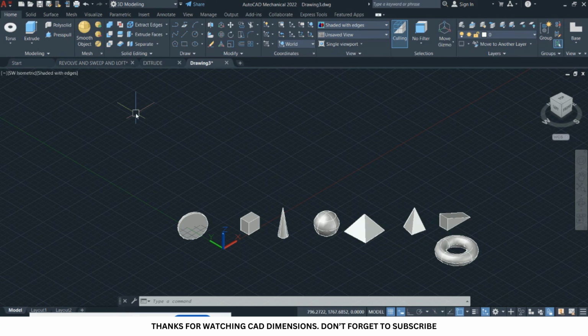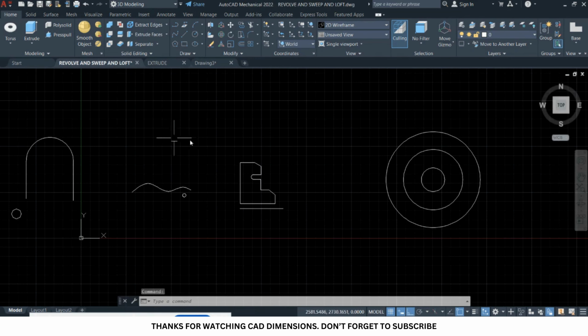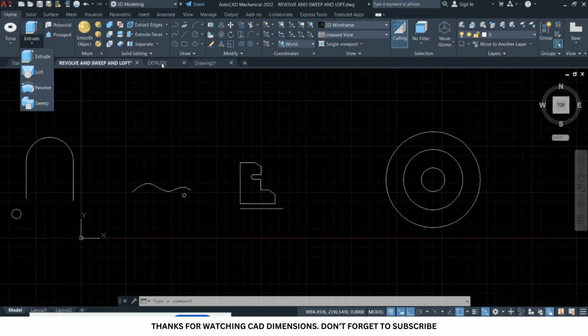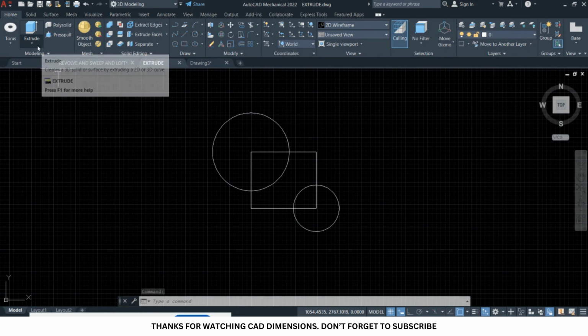Let's go back to what I wanted to show you, or what we will be learning for today. So today we are going to look at other tools. If you click on the drop down arrow, you will see extrude, loft, revolve, and sweep. So we'll be using these 2D drawings here to explain the basics of all of these particular tools that we have. All right, already we have an understanding of the extrusion, right? So I have created a drawing here and I've called it extrude. So I want to repeat the extrude again.